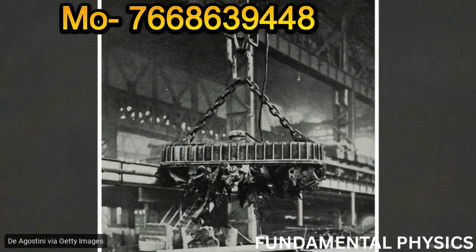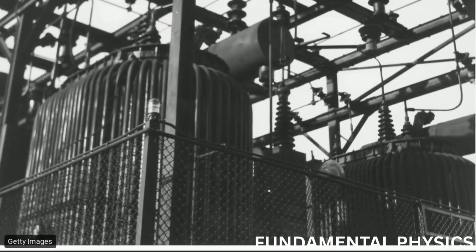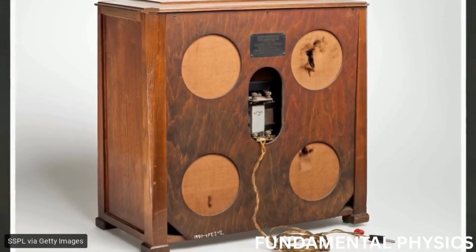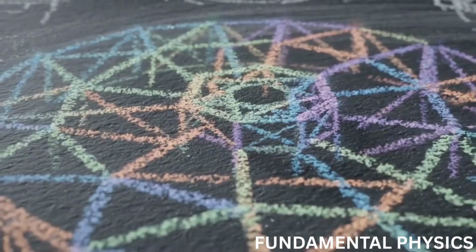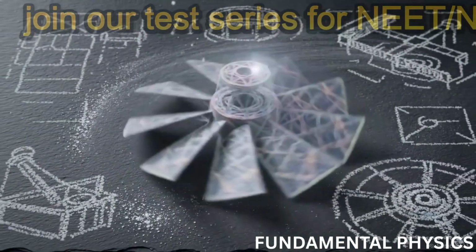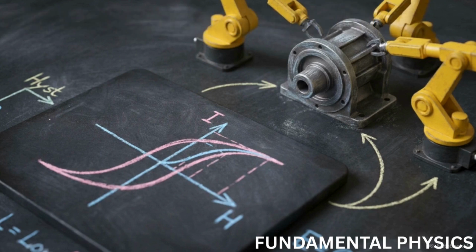Because soft iron sheds little heat, it operates safely in environments that rapidly alternate magnetic fields. It is the core material holding together industrial electromagnets and power transformers without melting down. Alternatively, steel's high coercivity protects its internal alignment from accidental interference, making it the required material for permanent magnets found inside loudspeakers and precision motors. The hysteresis loop establishes the boundary between a material's atomic response and its industrial utility. These measurements allow us to map invisible internal states directly onto the practical requirements of modern engineering.